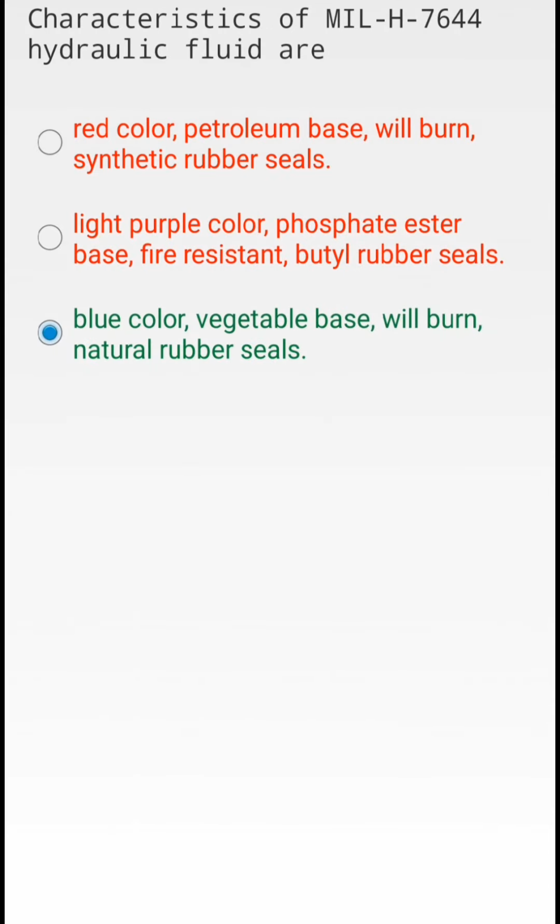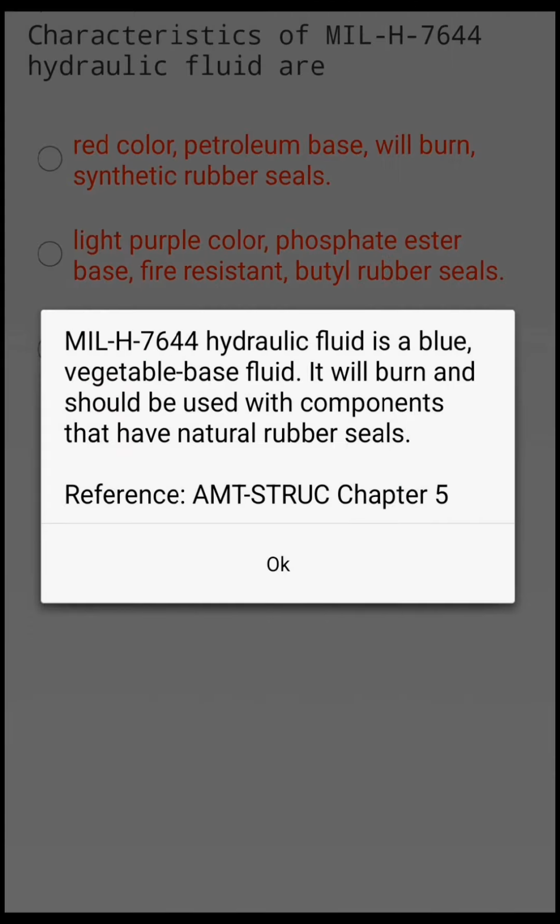Characteristics of MIL-H-7644 hydraulic fluid are blue color, vegetable base, will burn natural rubber seals. MIL-H-7644 hydraulic fluid is a blue vegetable base fluid. It will burn and should be used with components that have natural rubber seals.